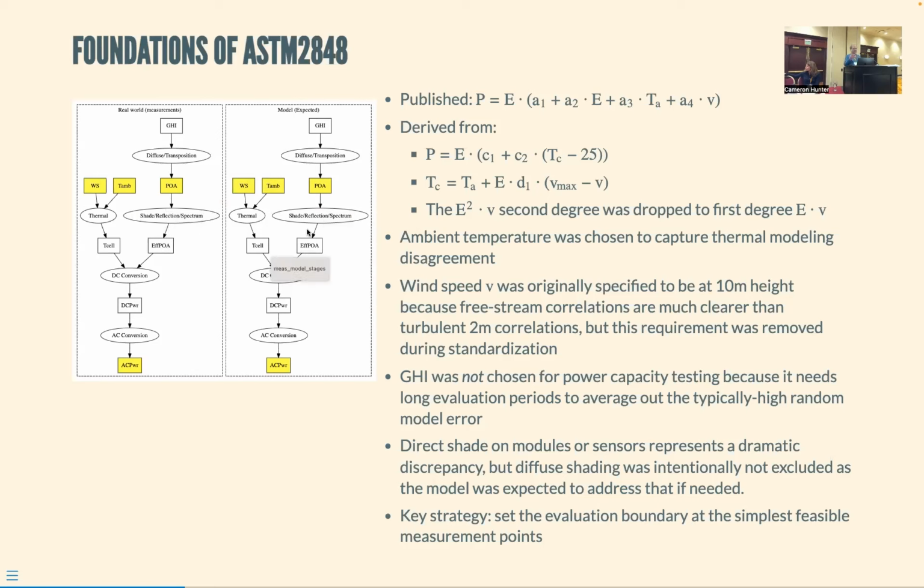PVsyst has an easy GlobInc measurement of POA that can be compared with a broadband pyranometer mounted in an unshaded, unobstructed area. And that's kind of the basis for how the test was thought of.